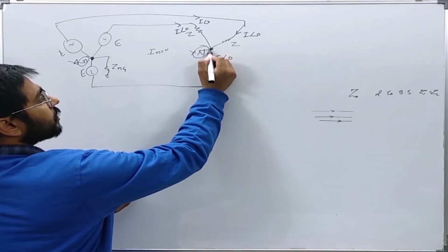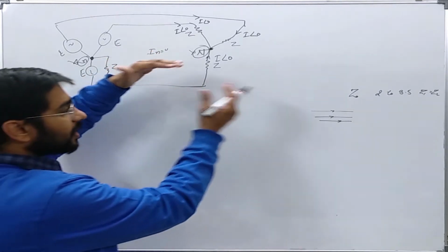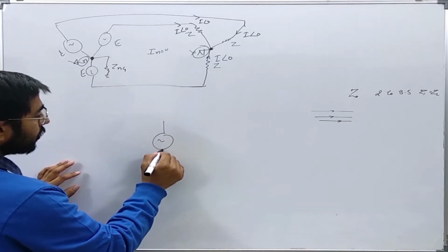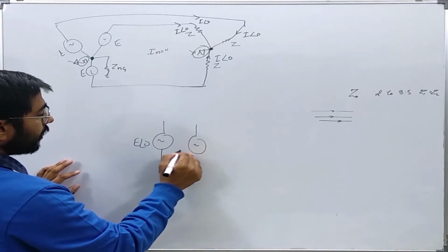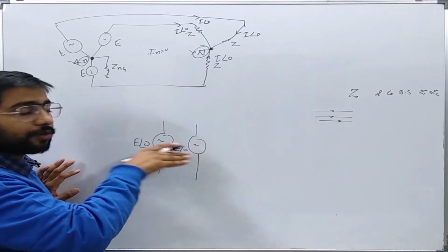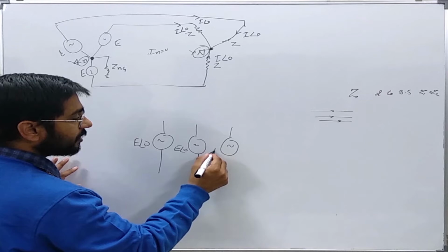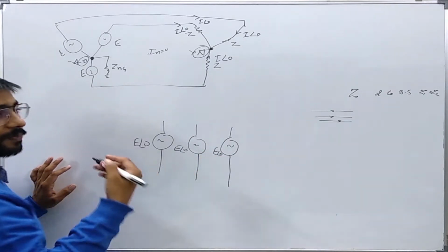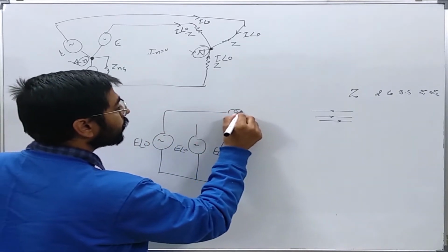at this point all these currents should be equal to 0. Or if I want to draw it in another form, I will show it like this: E angle 0. It will be E angle 0 if it is generating only zero sequence voltages, although in a usual power system there is nothing which can generate zero sequence voltage. Okay, so what is happening here now?